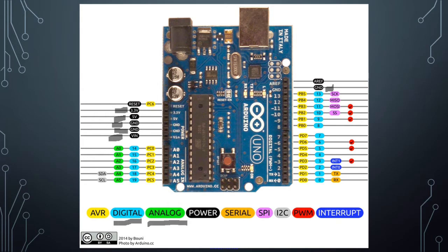And so you can see through all the blue, we have many, many digital pins. And this just clarifies too, as well, these little numbers in these blue ovals, what the pin number is. So you should be able to easily see the pin number on the board, but then these numbers provide you some alternates as well. So you'll notice on the left, the board says A0 through A5. If you want, you could also refer to these as pins 14 through 19 if you're just using them for digital purposes. That makes it a little bit easier.